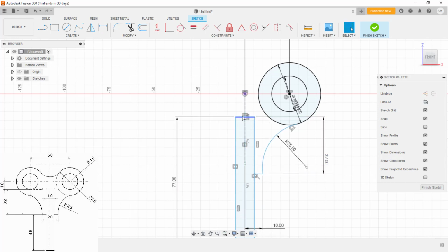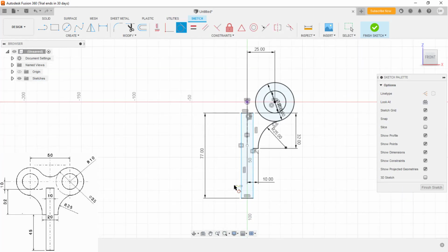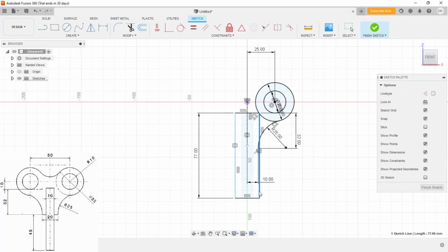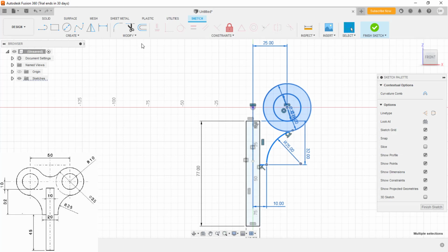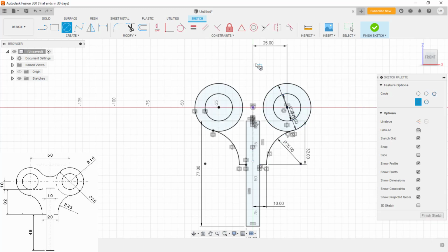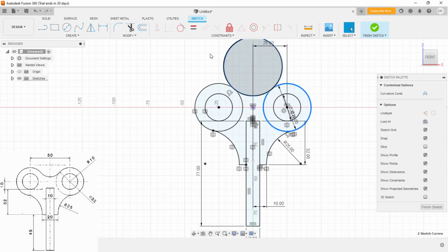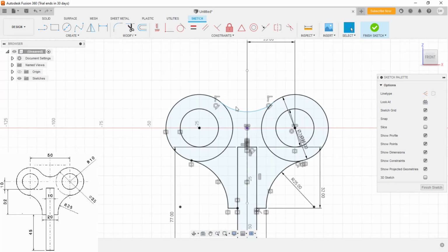So to define the relation between these two, it is tangent, but still it is moving, these two lines. Oh, thickness, I'll specify, escape, D shortcut, define the value, it is done. Done. Now I need to mirror these things only. I'll select them and go to mirror and just select the axis, green check. See the circle here, tangent I need, so I can select it now. Escape this also, I need the tangency, define it, trim it, and radius value, T shortcut, and define it as 20.